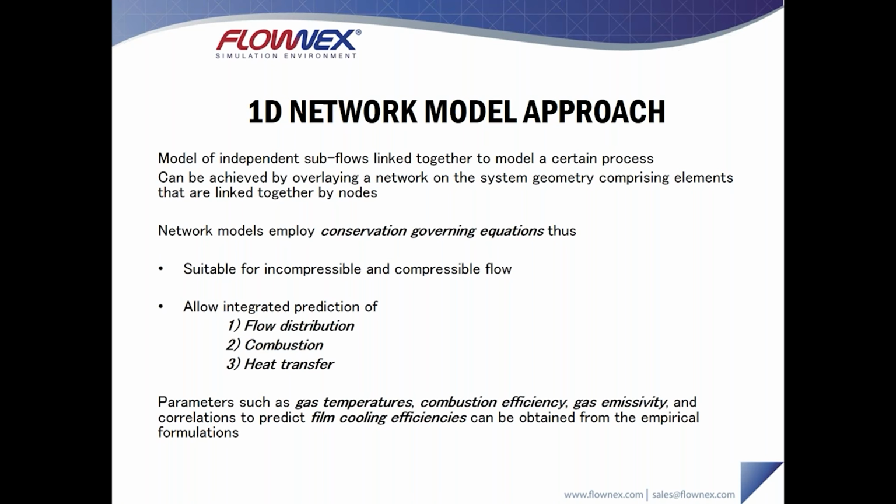So what that ultimately means is that we're able to determine and account for parameters such as gas temperatures, combustion efficiencies, gas emissivities, and then we can also incorporate correlations to predict film cooling efficiencies. And these are typically obtained from empirical formulations, and I'll be discussing those a bit more in detail later on in the presentation.